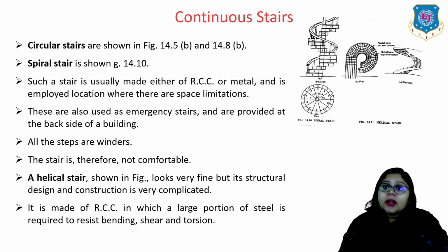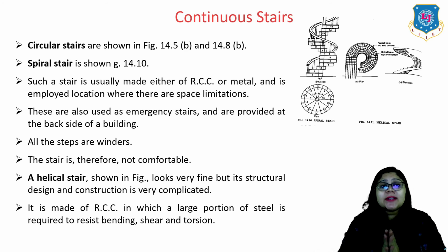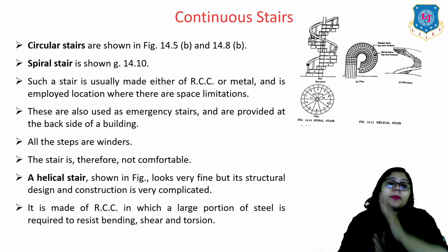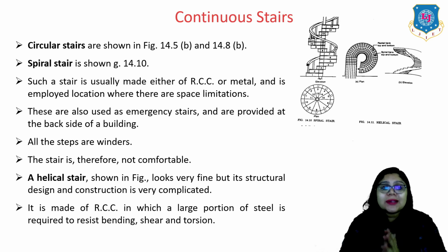Next is the spiral stair, which is again shown in the figure, where a spiral shape is there. Such a stair is usually made either of RCC or metal and is employed where there is a space limitation. Whenever we have space limitation, especially in commercial sectors where we don't have space even for parking and we have to reach higher floors, we go for this kind of spiral stairs. These are also used as emergency stairs and are provided at the back side of a building. All these steps are winders and the stair is therefore not comfortable like the other ones.